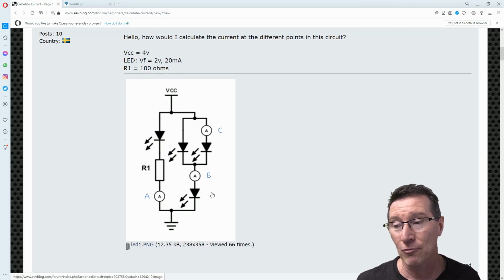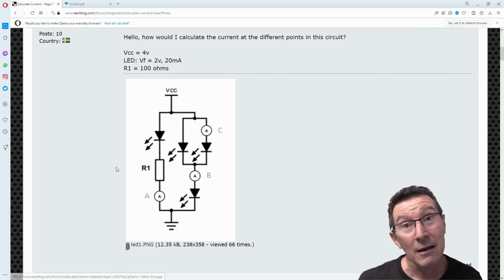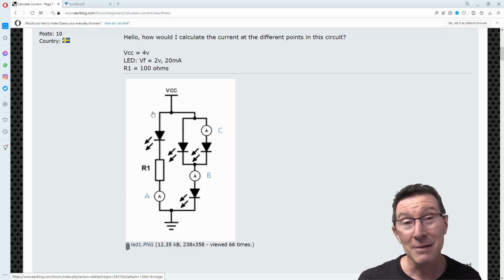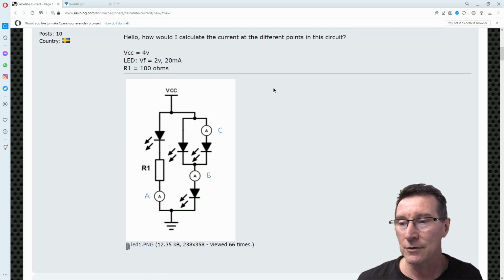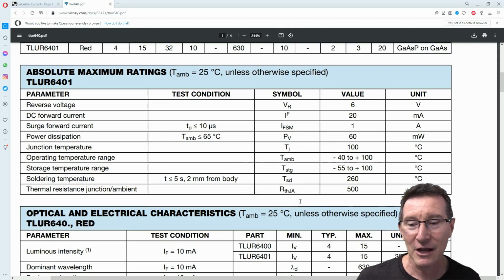And these diodes on the right-hand side, they've just got to sort themselves out. But this one over here, nicely designed with this current limiting resistor, then yes, it's going to get the proper 20 milliamp treatment there, assuming you've got the exact LED that gives you that exact value. But even then, you're going to have temperature and process variations, manufacturing variations over here.